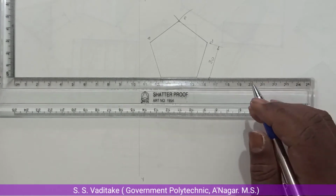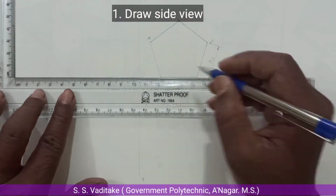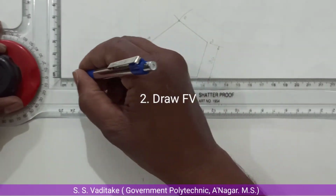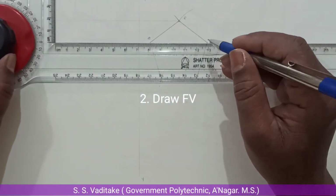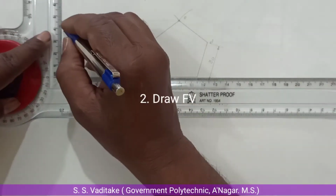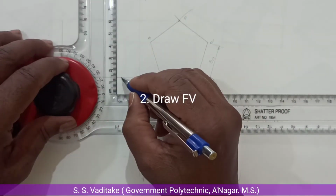As the axis of a pentagonal prism is parallel to both planes, at first we have to draw the side view in which we have to show a pentagon. Label the corners of the pentagon and project the projection line through these corners and draw its front view.